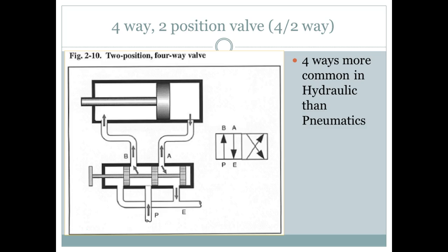The problem with pneumatics is that if I put the flow control on the pressure side and leave the exhaust side open, the cylinder is really jerky because it has nothing to push against. It's got compressed air, and as soon as the cylinder moves, the air uncompresses a little bit, and then it has to compress back. So on pneumatic valves we put the throttle in the exhaust.